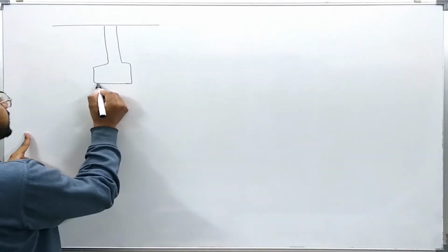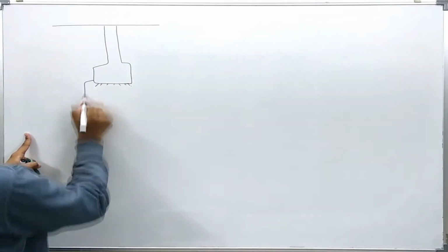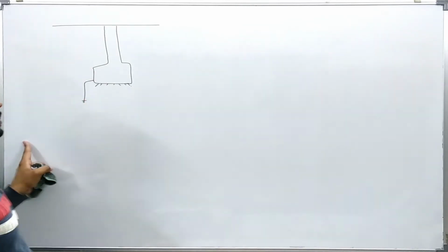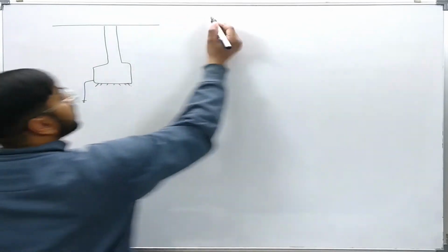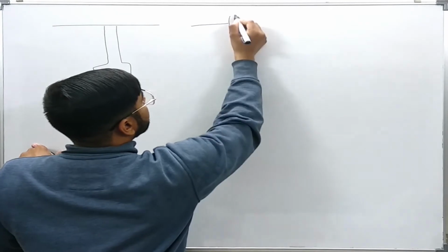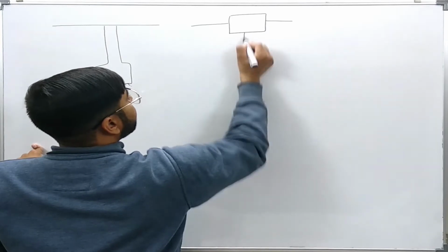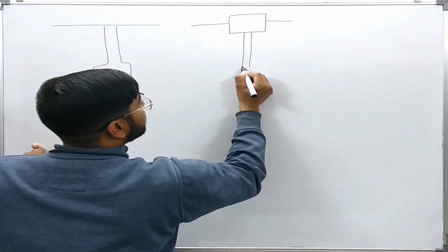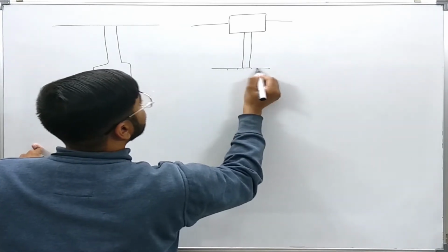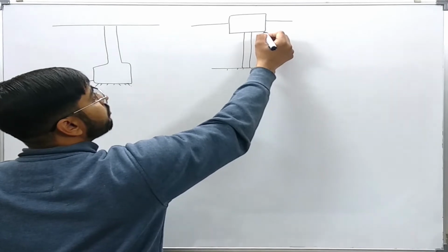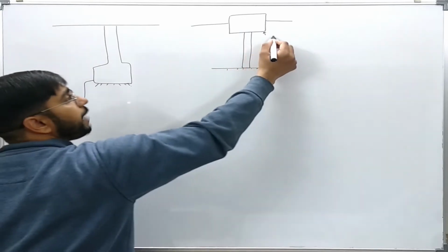If this tank is connected to earth, like this, then it is called a dead tank CT. If we have a CT like this, the tank is here, transformer oil is inside it, and it is standing on some insulation, and this is the floor. So this is at live potential, not at ground potential. So it is the live tank CT design.